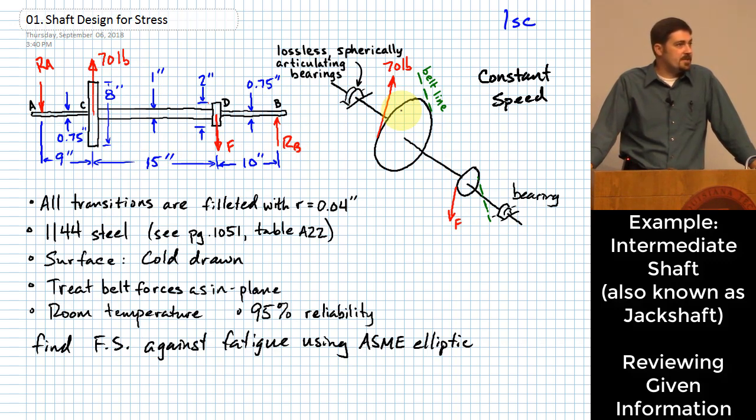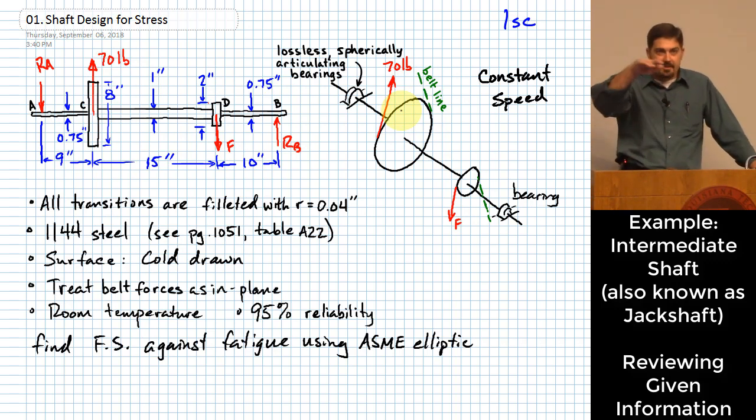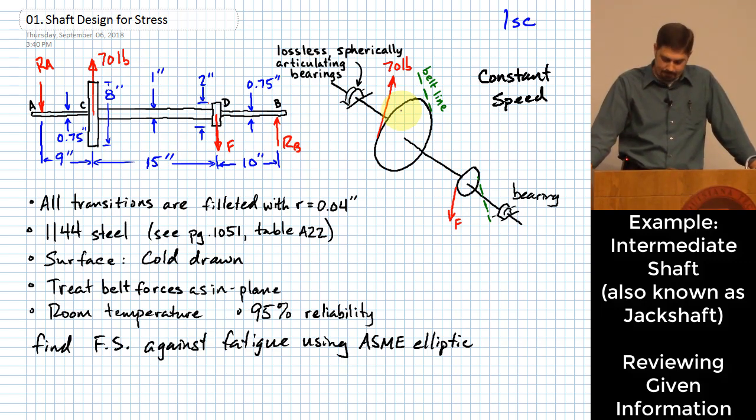Endurance limit is basically the amount of stress that a material can carry and essentially last as many cycles as you want to apply at this stress level. It's generally lower, always lower than the failure stresses like the yielding stress or the ultimate stress. That endurance limit is affected by the temperature of the material being stressed.